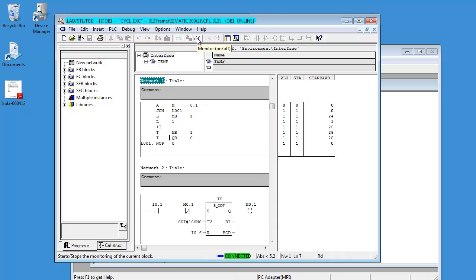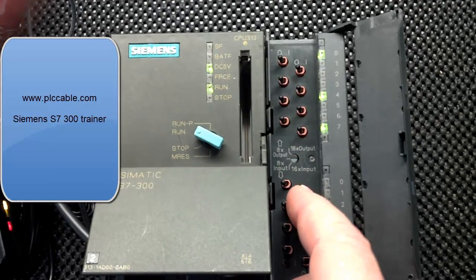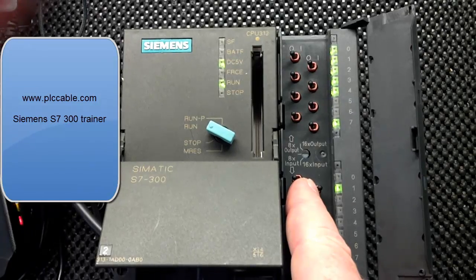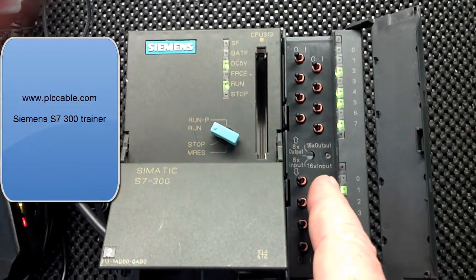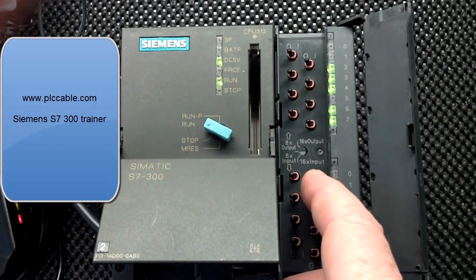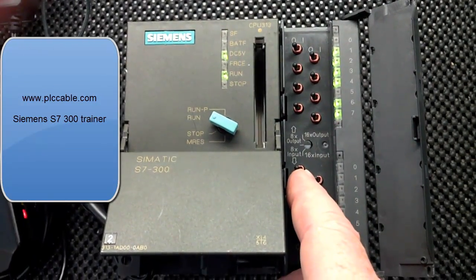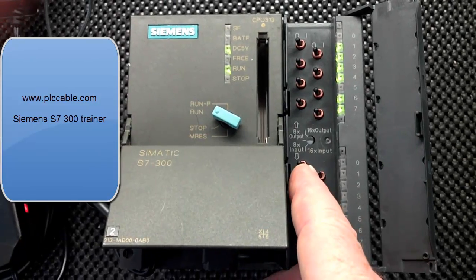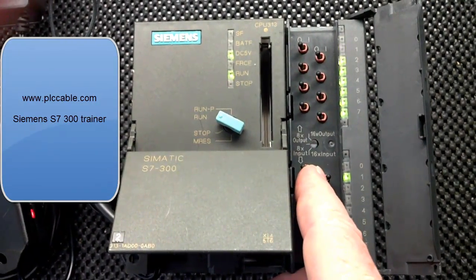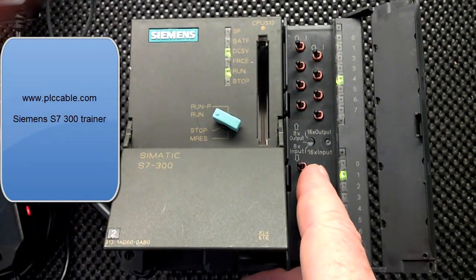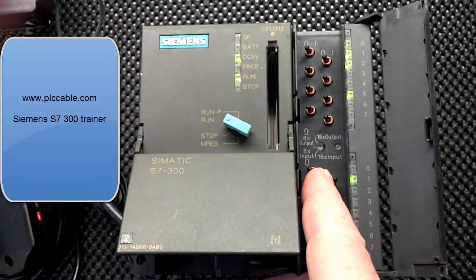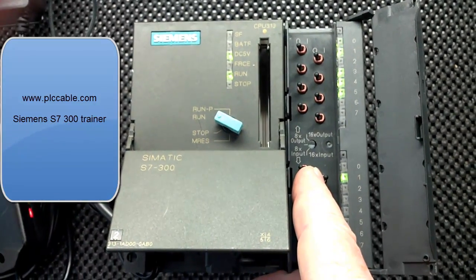So this is the card I was referring to. It's a 3742XH01. And you'll notice that when you turn the switch to the off position, the LEDs on the top stop running, and that means the program is stopping the logic. If you turn it to the on position, then the LEDs start moving again, and it's adding a numerical value of 1 to that output word for every 1 millisecond. You should go back and take a look